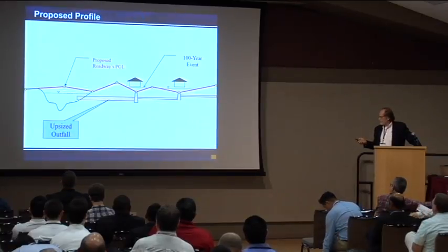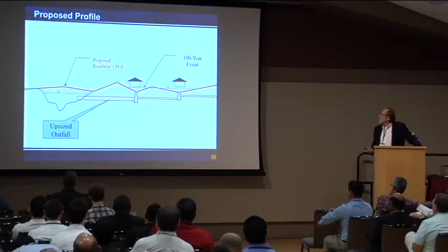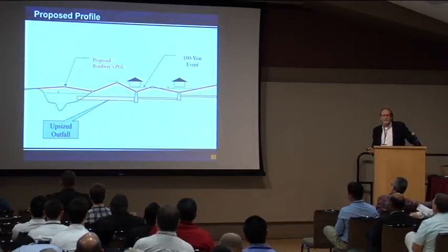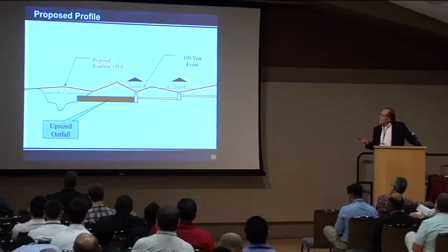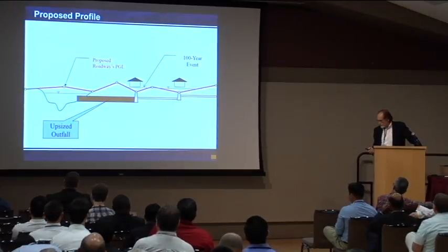If, let's say, that VPI is a constraint and you're not able to move it, the other option is possibly to consider a structural option, and that would be to increase the size of that structure and allow the extreme event to enter the structure via inlets at this location. So you want to make sure that you size those inlets accordingly as well.